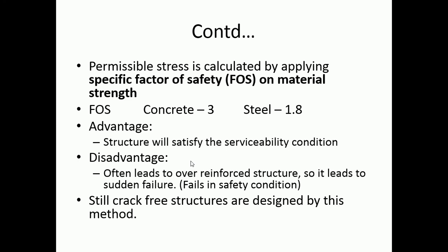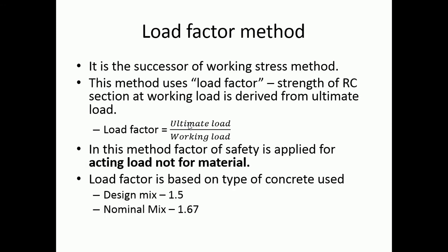Okay, but though it has some limitations, we still use this method for structures wherein we require that no crack should be formed. Like water retaining structures, where formation of cracks would be a dangerous thing. In those cases we'll be using this working stress method. Still people are using this method.